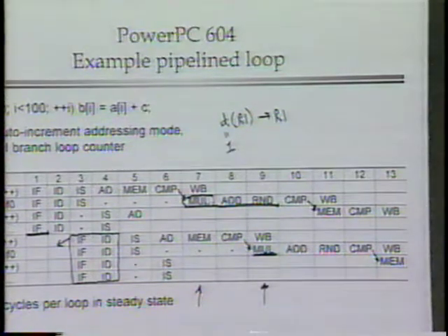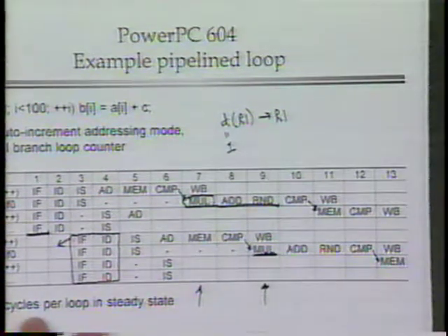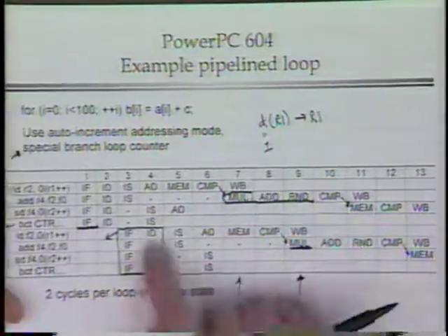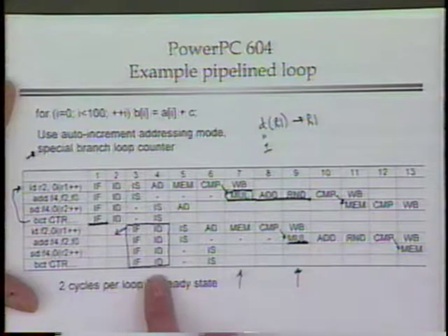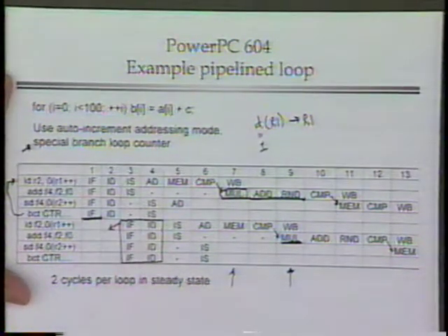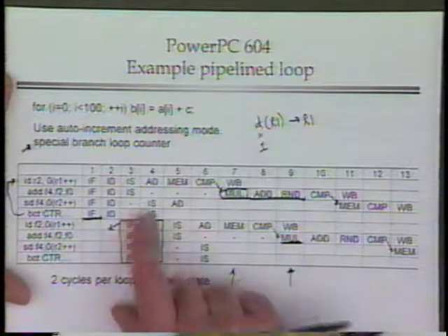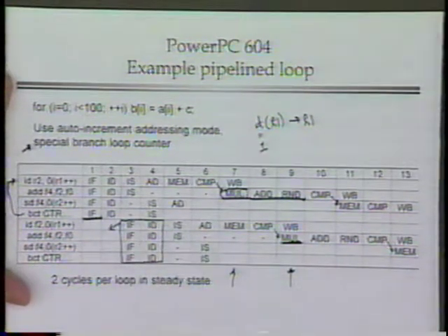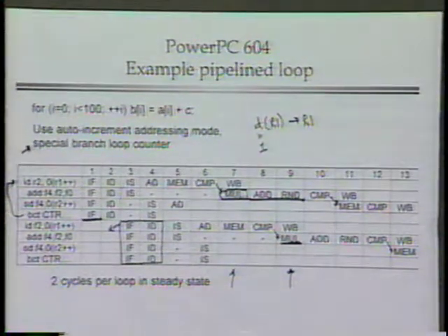which is a lot better than the alpha chip, which was, what, 7, 9 cycles per loop, something like that. But these cycles are obviously taking a lot more time. The clock is much slower. It gets a fair bit of parallelism. We've been able to fetch, although not issue, 4 instructions in parallel. We've been able to issue 2 instructions in parallel. So it's working pretty well. Obviously, still a lot of stall cycles, but good performance nonetheless.